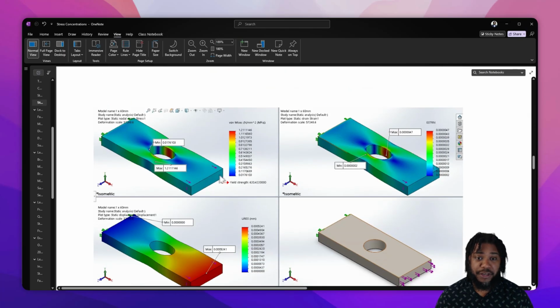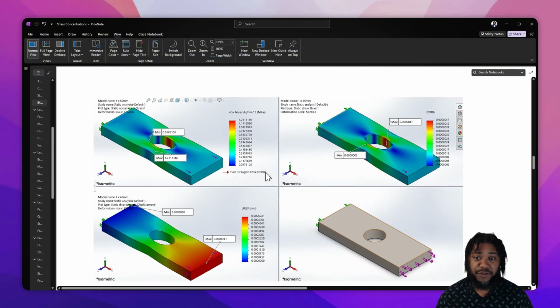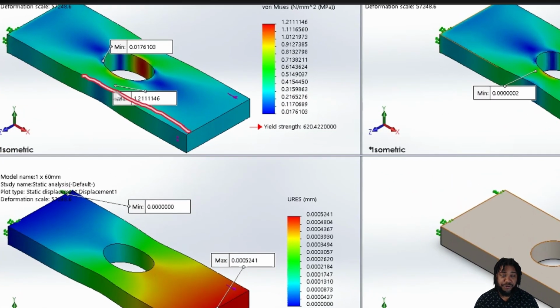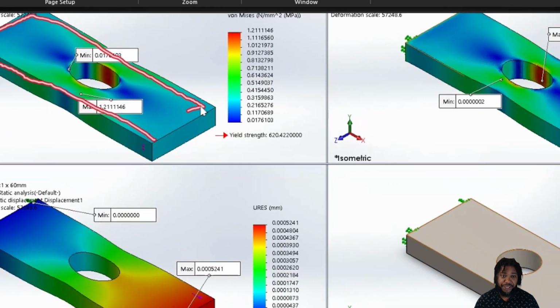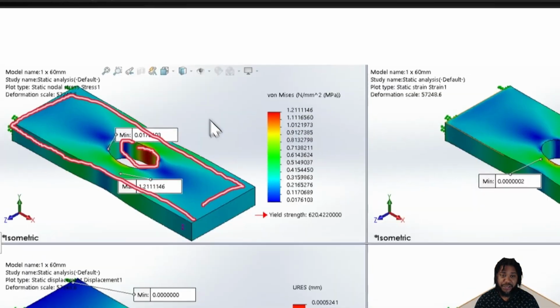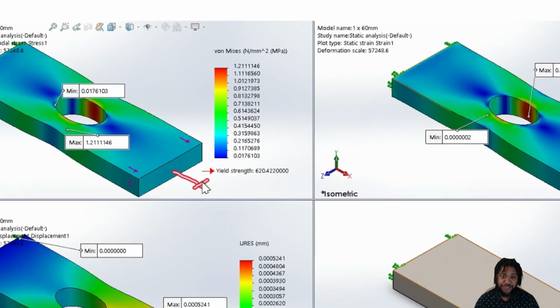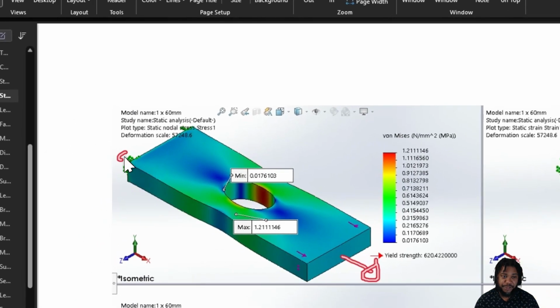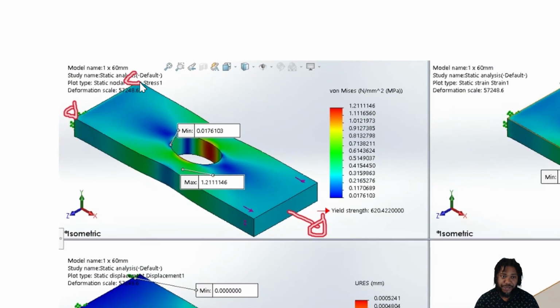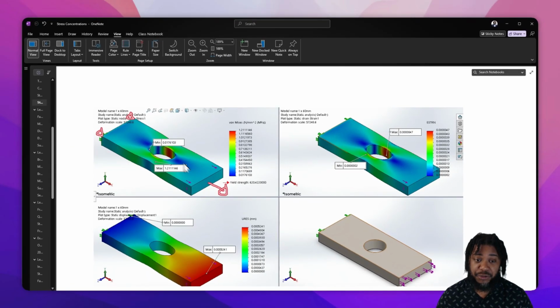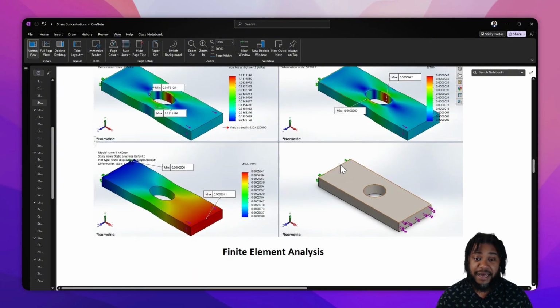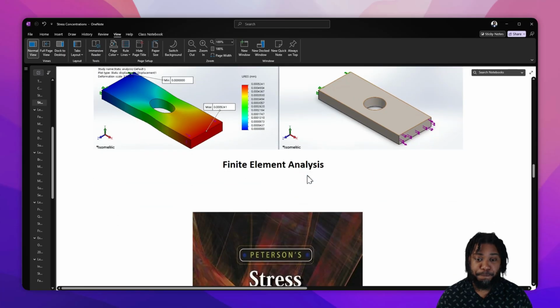Now, in terms of FEA, it's fairly simple. You'll create your geometry, you'll put in your discontinuity, you will apply boundary conditions of load and displacement constraints in order to constrain your object in space, and then you'll simulate the stress field, and from that simulation be able to calculate what the value of that max stress is, right?